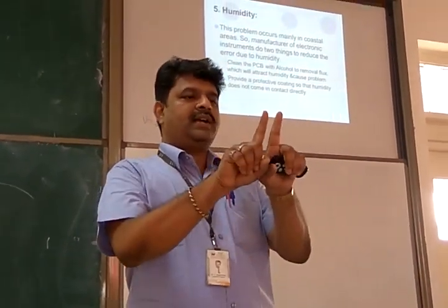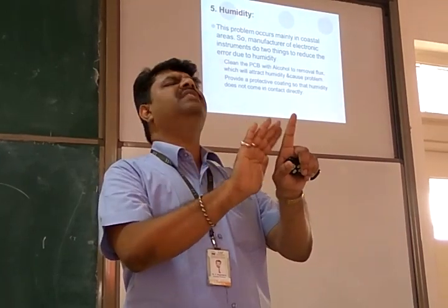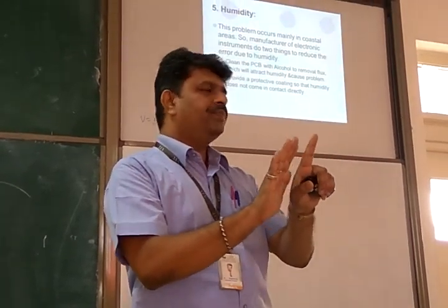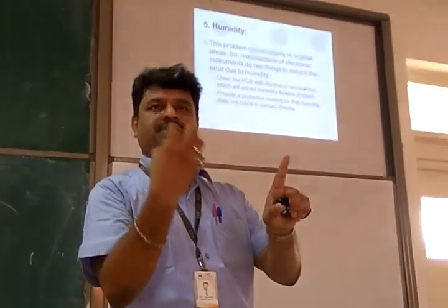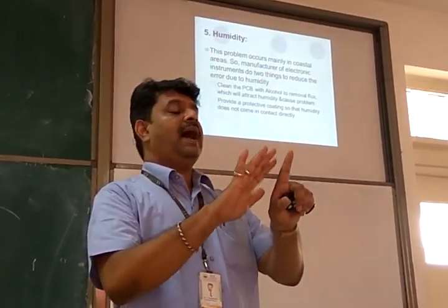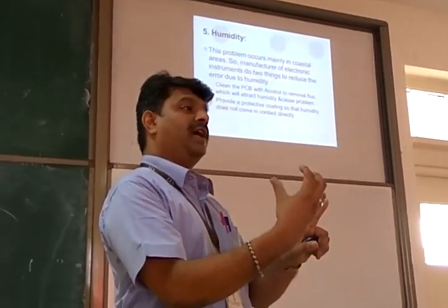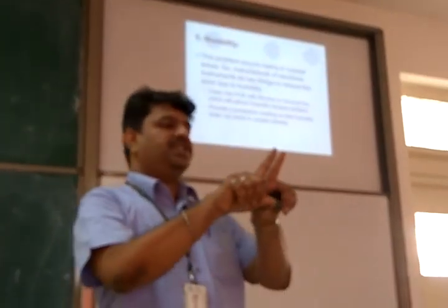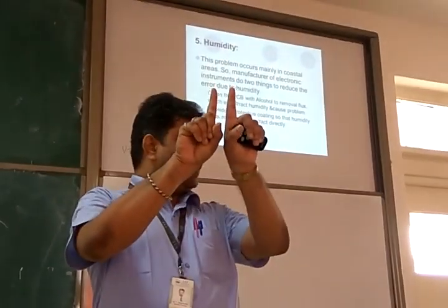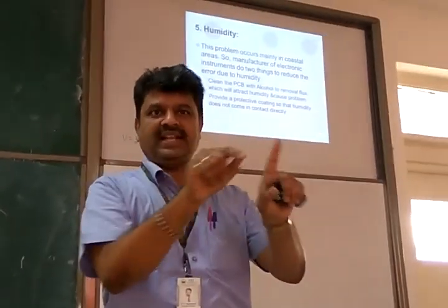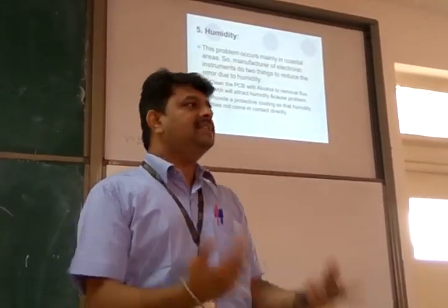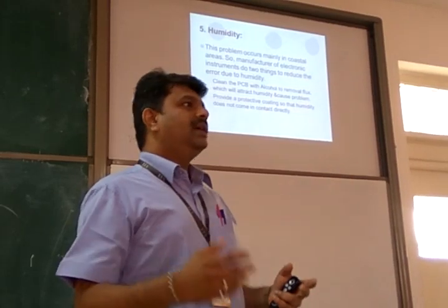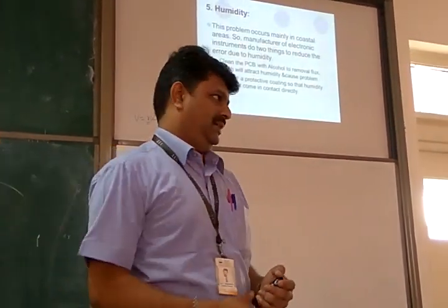Track 1 and track 2, above which there is a thin layer of flux, absorb moisture during the winter season and will have a good amount of water to conduct between the two tracks. So the two tracks either get connected, resulting in a short circuit, or create some capacitance effect, creating some noise while you are talking.